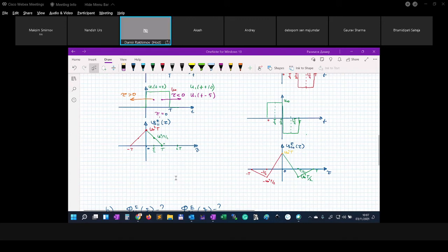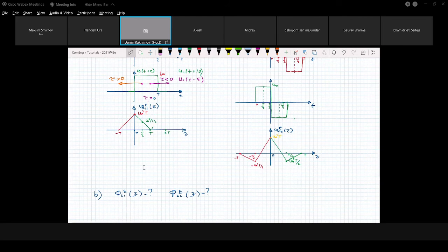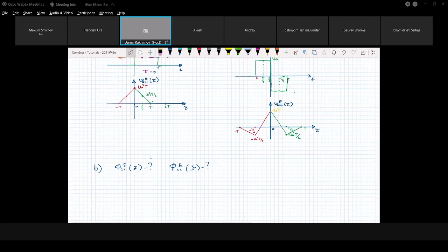We ask you to write an expression for the correlation function itself, for the resulting signal that you get. And then you can have this such question. And this is what we're actually going to do at the moment, because we need to find energy spectral densities. The easiest way to find it is to calculate the Fourier transform of the correlation function. And in order to calculate a Fourier transform, you need to have an expression for the correlation function itself.